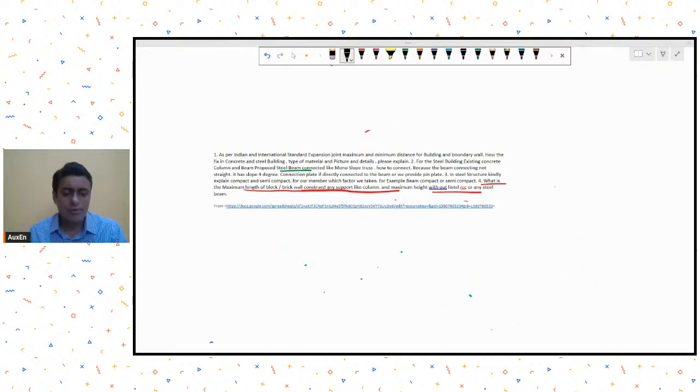Now, most of the time, you will say that it is only a partition wall, so it does not have to take any load. But still, there are some slenderness limits also for the brick wall. And if you have a mid to high rise building, then that brick wall also has to take lateral loads in the form of wind. That brick wall also may have to take some lateral load due to any seismic effect because of the self-weight of the brick wall.